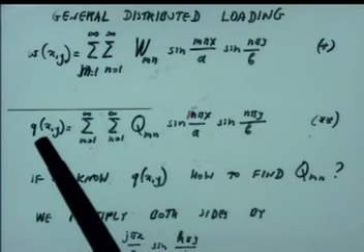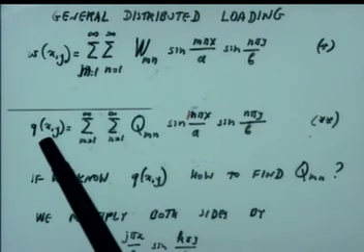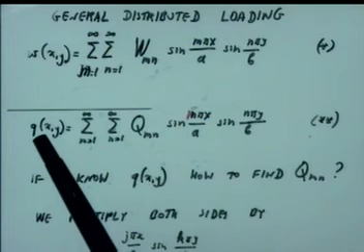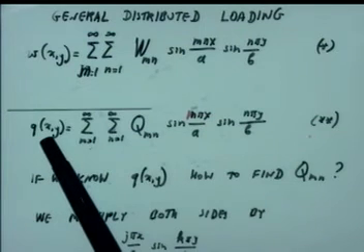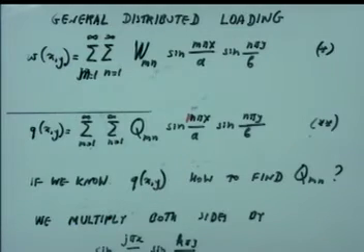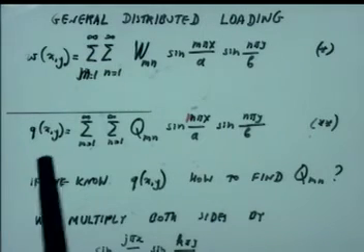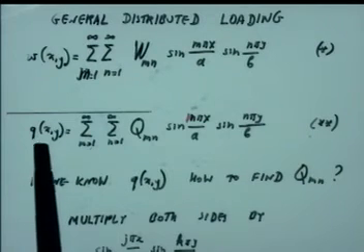Now the loading, please write it down, Q(x,y) we know. I can just measure point by point, so to say. For example, if it is snow, then I can just take a meter and stick it in various places, and I know the height. And then I will multiply by density, and I will calculate what Q is. So Q we know. Please write down, Q is known.